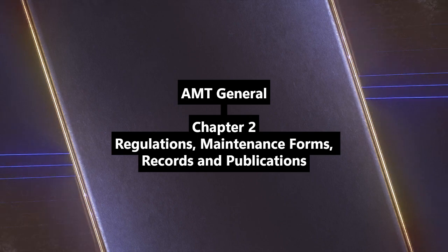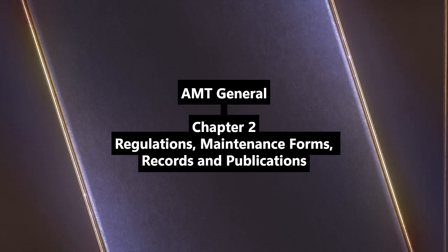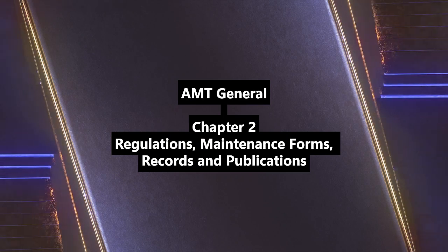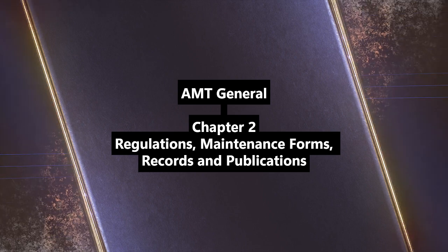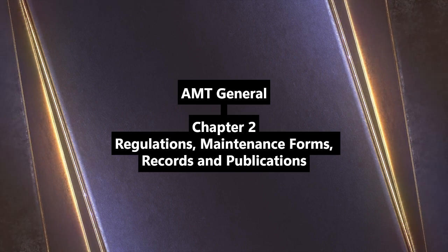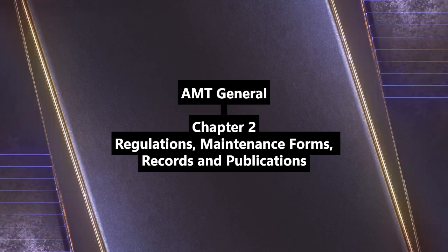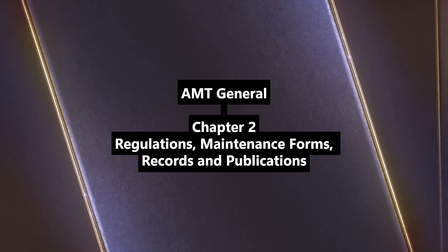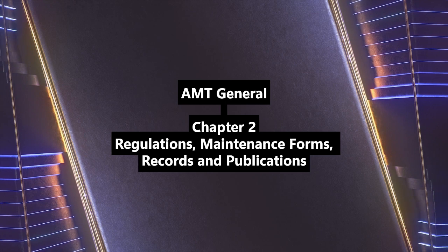What kind of manuals do manufacturers provide? Airplane flight manual, AFM, serial specific, or pilot's operating handbook, POH, model specific, often the same thing now, required on board. Maintenance manuals, AMM for whole aircraft, CMM for components. Service bulletins, SBs, usually advisory unless tied to an AD or inspection program. Structural repair manuals, SRM for structure repairs, often separate for large aircraft.